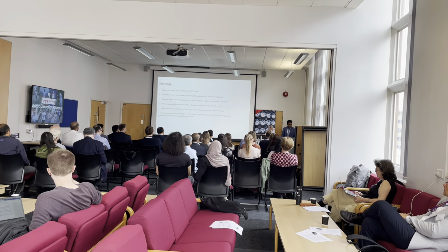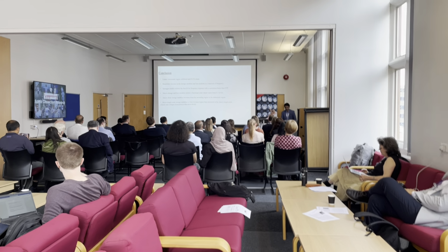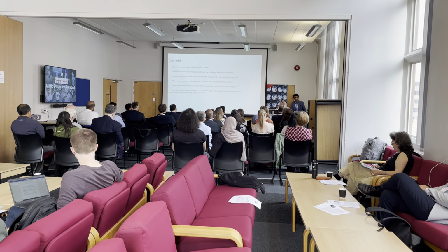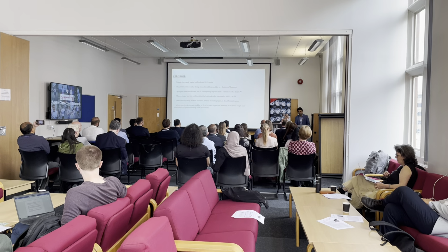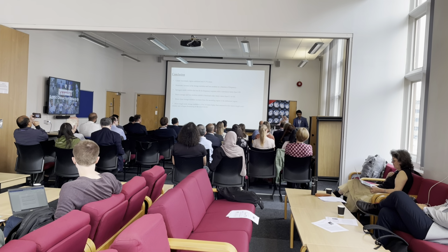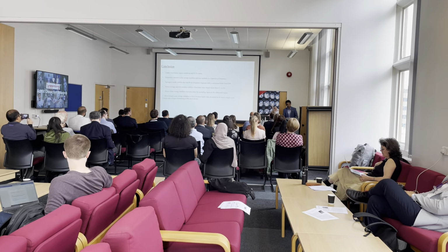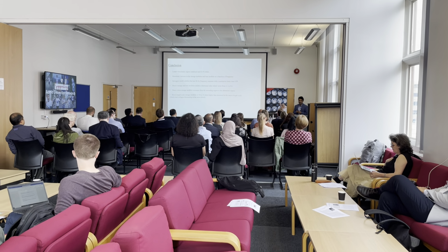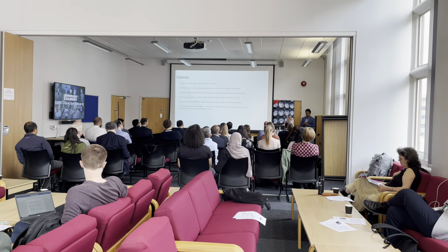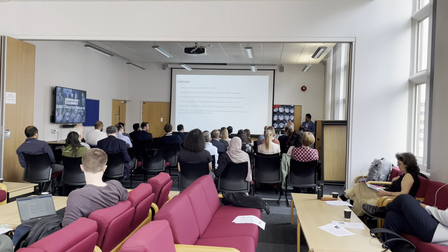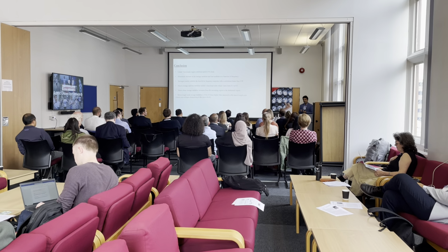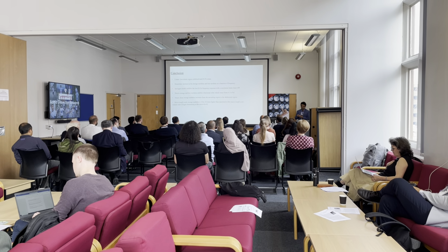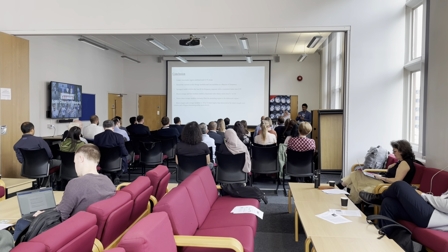One of the other interesting parts was that the micro length scale storage and loss modulus, specifically the storage modulus, was approximately 10 to 16 times higher compared to the macro length scale storage modulus. The potential reason, I think, is that these collagens and elastins behave far stiffer at the micron length scale compared to the overall bulk tissue, because in the overall bulk tissue we had a huge number, n number, of layers of elastins and collagen, one above another.